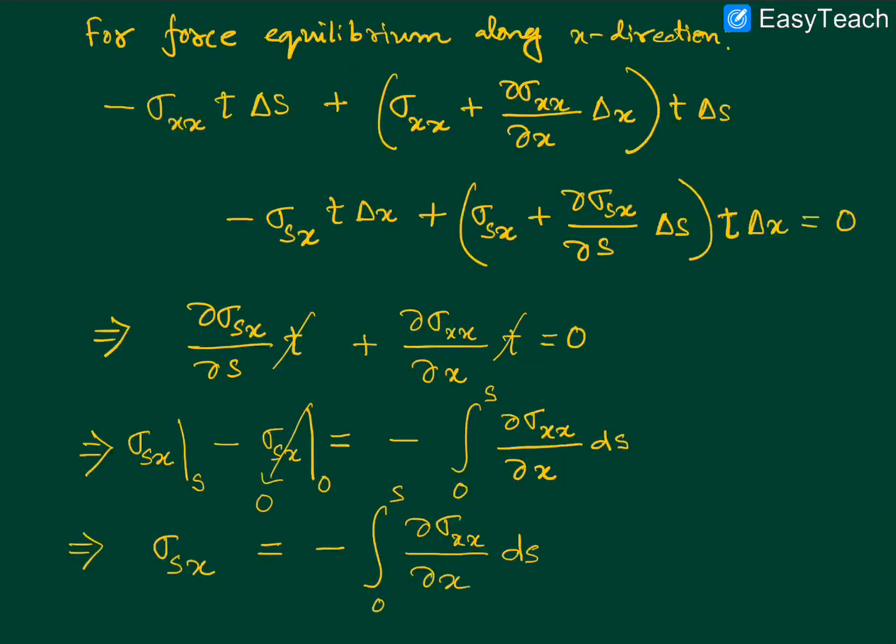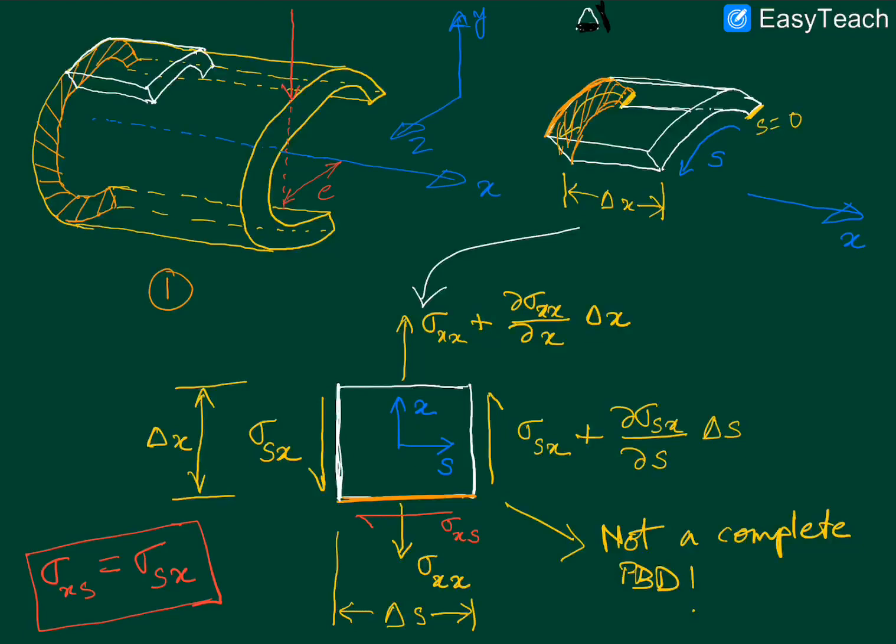So what I mean to say is, if we go back to this diagram, the Vy will be a result of the entire distribution of shear stresses here in the vertical direction. So if we are considering a particular length from this end, the Vy, the shear force along the vertical direction, will be a given constant. In fact, for this particular problem, along the entire length, the Vy will be a constant, equal in magnitude to this externally applied force.